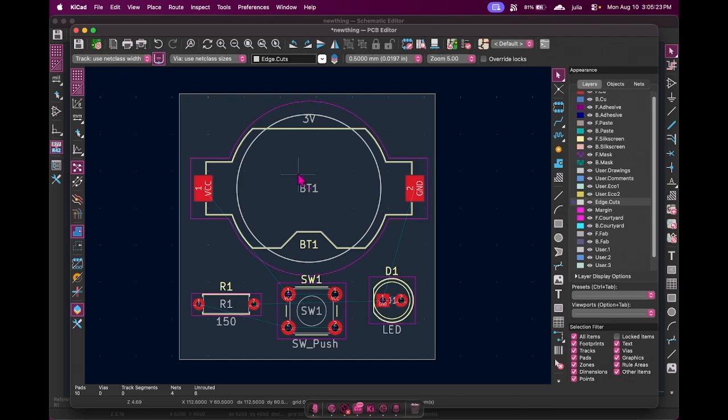But don't connect the ones that have the word ground on them. Let's say GND. That's where we're gonna use the ground plane, and I'll get into what that is in a second. What happens if you do? You can, but you guys should learn to use and generate a ground plane. For this one, it's not needed, but you should, because when you get into a use case where you have components with multiple pins that need to be connected to ground, having so many traces connecting to ground is painful. So this is better.